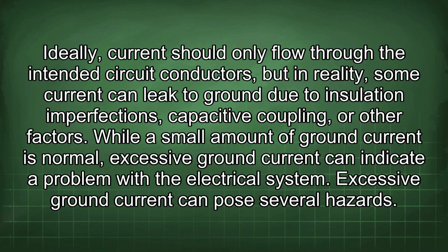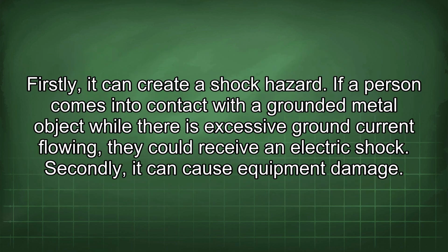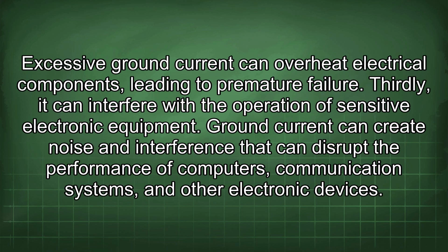Excessive ground current can pose several hazards. Firstly, it can create a shock hazard. If a person comes into contact with a grounded metal object while there is excessive ground current flowing, they could receive an electric shock. Secondly, it can cause equipment damage. Excessive ground current can overheat electrical components, leading to premature failure. Thirdly, it can interfere with the operation of sensitive electronic equipment. Ground current can create noise and interference that can disrupt the performance of computers, communication systems, and other electronic devices.